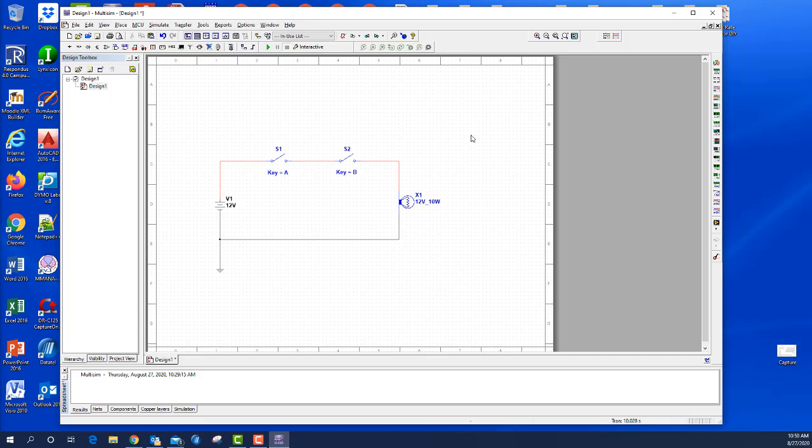We're going to do a simple measurement, and we're going to go and grab the multimeter, which is the very first instrument over here on the far right in that column. And see, now I have a multimeter, and I'm going to put it right there on the screen. And now a multimeter has a positive and a negative lead. They're like probes that you hold in your hand, and you can measure voltage. Some of you probably used a multimeter before, or a voltmeter. And so that's what we're going to do. We're going to measure the voltage coming to this lamp.